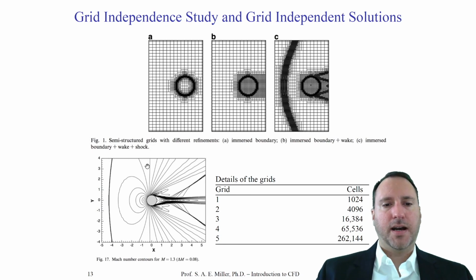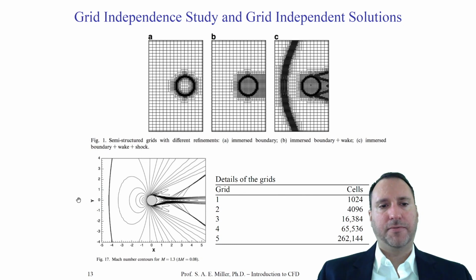We can see one contour of this particular flow field in the lower left corner. Here we have the black line, which is the shock, the bow shock. The flow moves left to right, and we see pressure contours forming around the cylinder. There's the turbulent wake, and then here are shocks too.